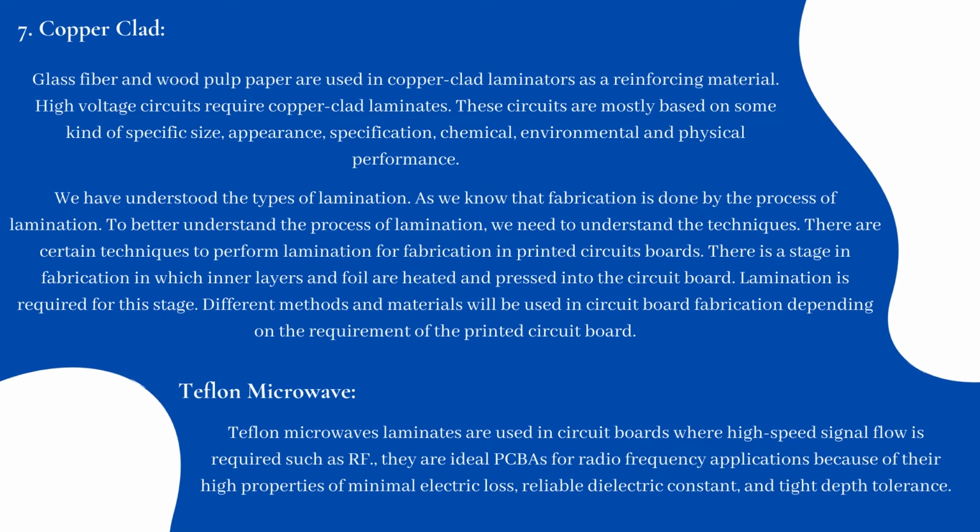Teflon microwave. Teflon microwave laminates are used in circuit boards where high-speed signal flow is required, such as RF. They are ideal PCBs for radio frequency applications because of their high properties of minimal electric loss, reliable dielectric constant, and tight thickness tolerance.